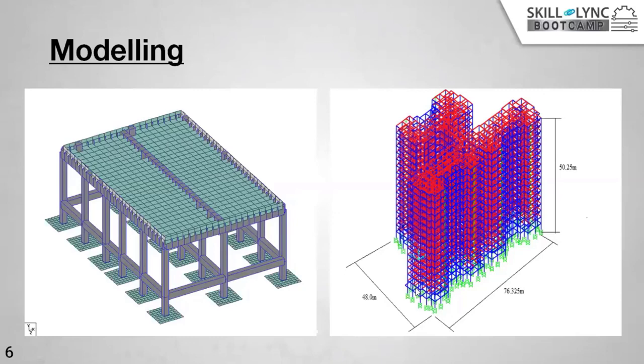So the first basic step is to position the column points in the software. How can we do that? In STAAD Pro, we have to define the nodes. We can type all the column locations as nodal points, with XY coordinates. The Excel can be directly copied to STAAD Pro, or we can directly copy to the editor file in STAAD Pro.